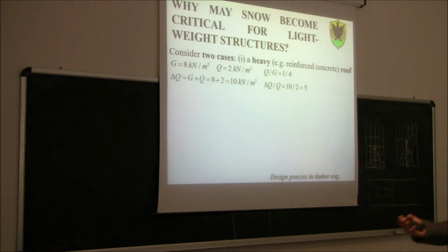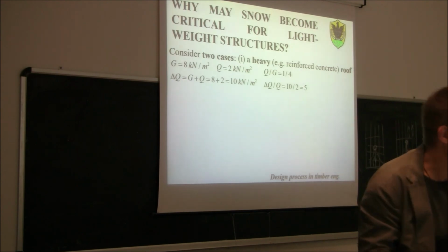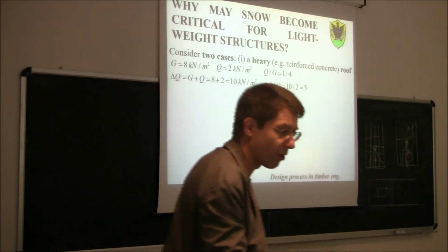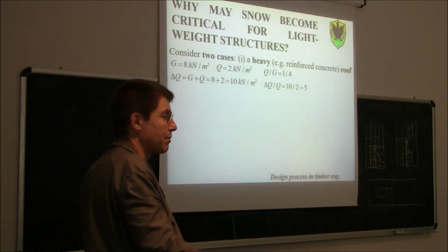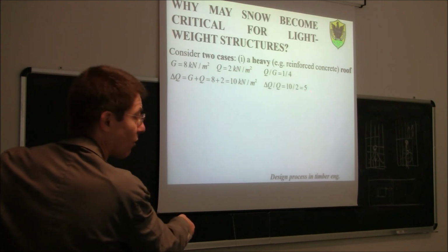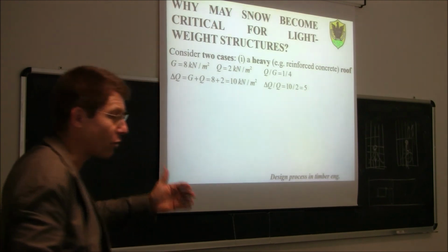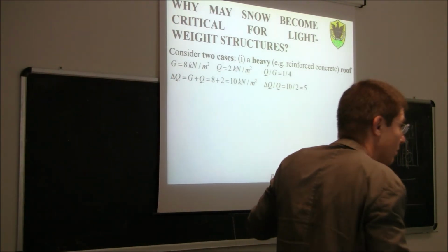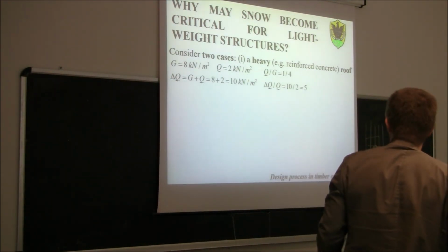I never had something like this. Usually you have steel floors or timber floors that collapsed, timber roofs that collapsed because of the snow. And now we understand why. Because you see, with reinforced concrete, you have a safety coefficient in terms of snow of 5 times the design load before you reach failure.